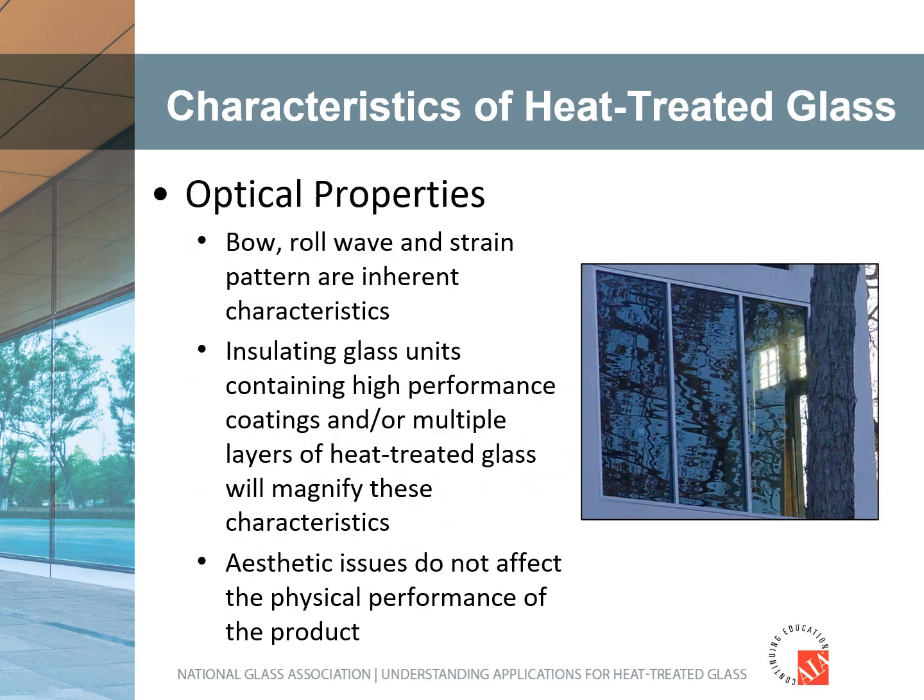Another important characteristic of heat-treated glass is its optical properties. Residual stresses induced by the high heating and rapid cooling cycle can result in surface deformations, such as bow, sometimes called warp, and roller wave. The former is caused by non-uniform stresses in the glass that can result in an edge-to-edge curl, or smaller localized depressions.